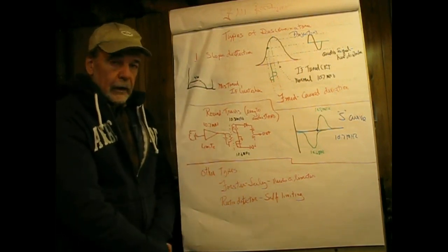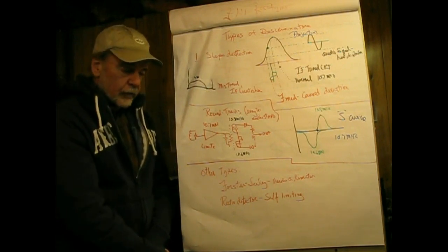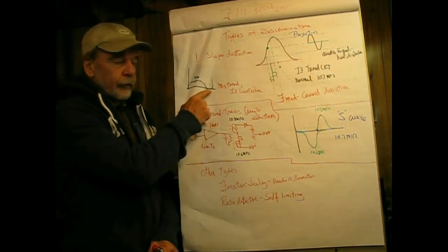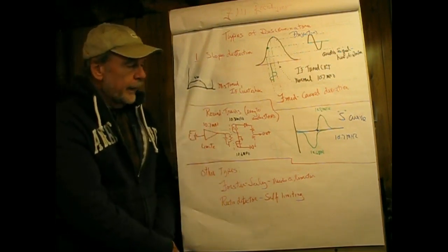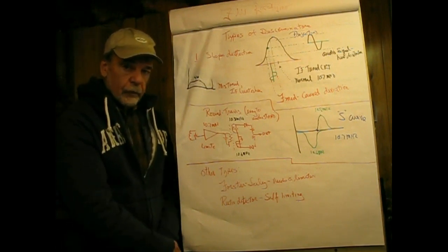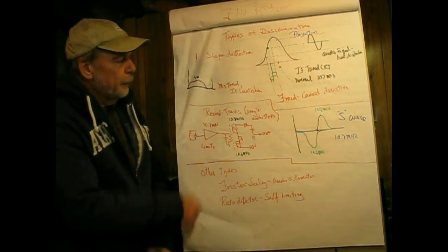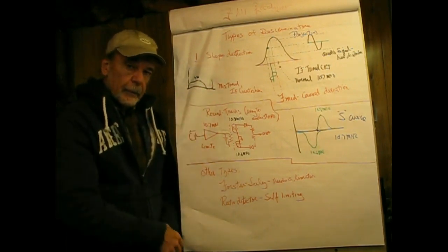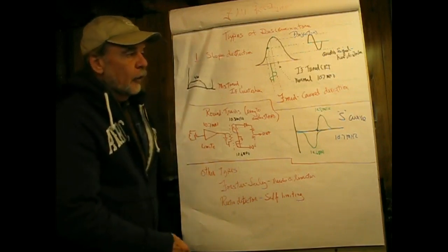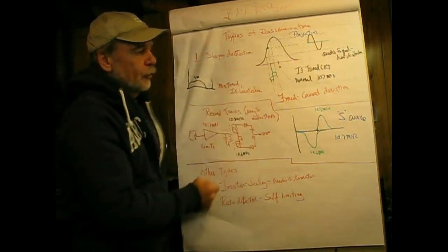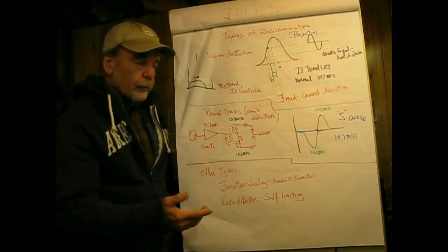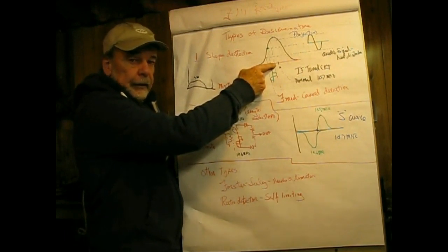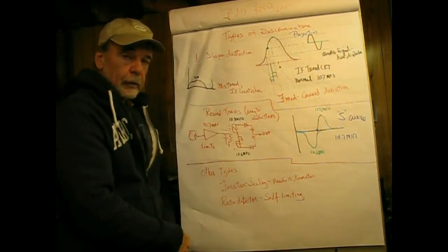So World War II came, and manufacture of radios and television sets was basically curtailed. And after the war, because of noise interference in AM, the FCC mandated that the carrier in this be frequency modulated. So people, not many, but people bought the sets with AM detection. So to make their sets work on FM, they called technicians out, and all they did is mistune the intermediate frequency stages. So ordinarily, the intermediate frequency would be exactly in the center of the response of the intermediate frequency